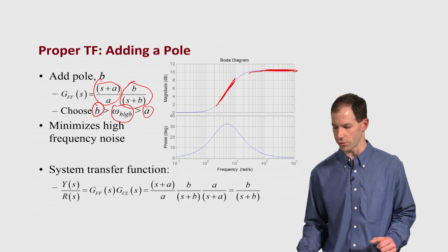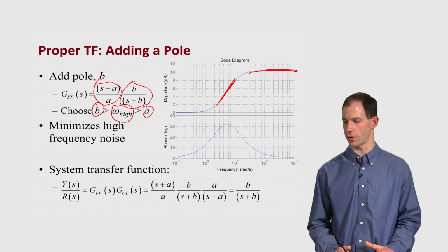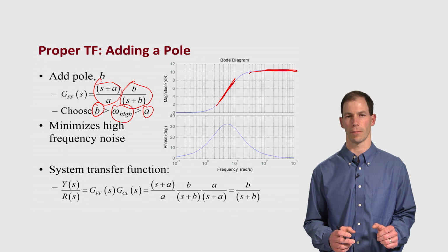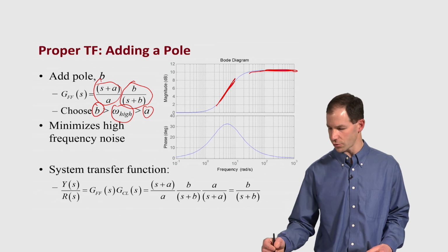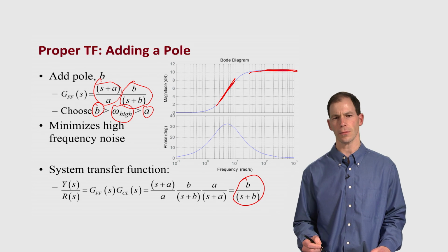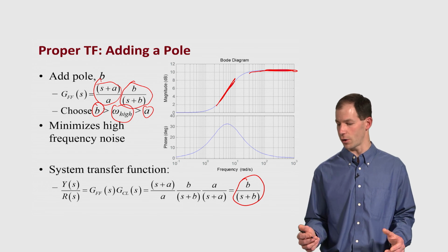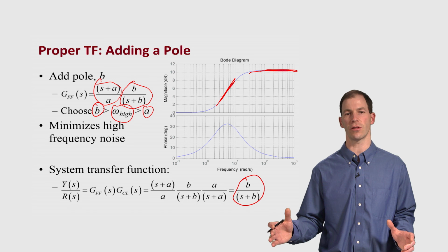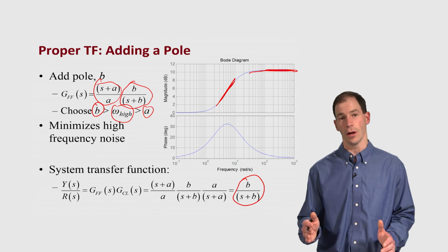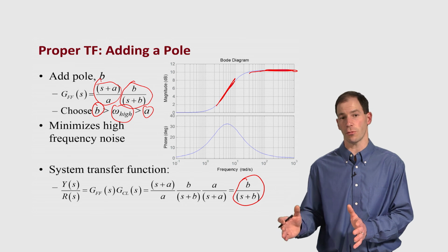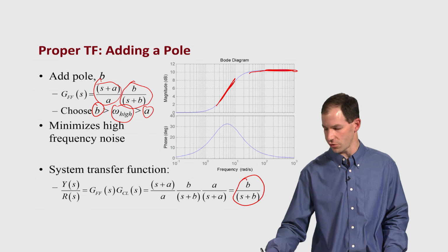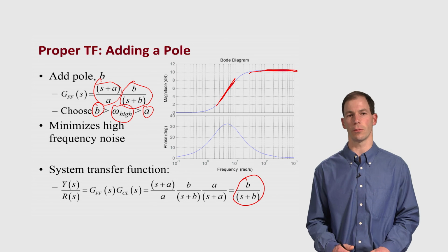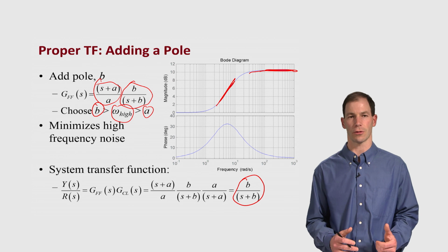So what happens when we put all this system together? Well, here is the full transfer function of the system. You'll notice that I started off with a closed loop transfer function that was A over (S plus A). And once I multiply this out, I end up with a transfer function that is of the exact same form. And you say, well, why is this any better? The reason it's better is because these values of B are much greater than the values of A. So we have extended the range that our system is able to operate at, and basically be able to now run at higher frequencies and have much better tracking up to higher frequencies, simply shifting everything to the right. So we get a much better operation of our system by adding this open loop controller in front of our feedback controller, creating this feed-forward system.